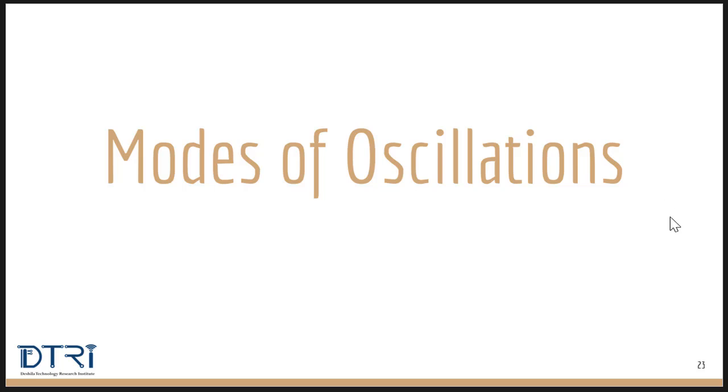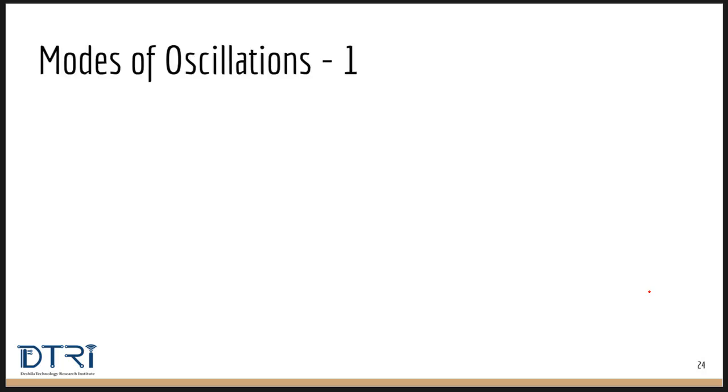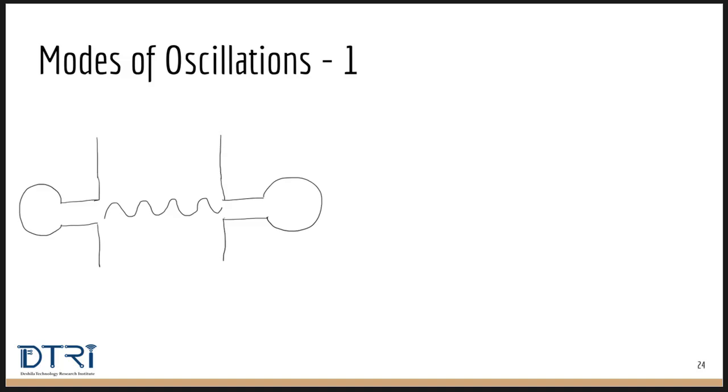In this lecture, let us learn about modes of oscillations. Let us see how the bunching of electrons creates a sustainable microwave signal. In the previous slides, we saw one cycle of sine wave creating the bunching effect. In reality, the cavity resonator is creating such sine waves continuously.